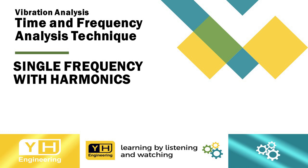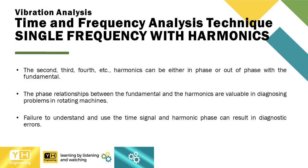Vibration analysis. Time and frequency analysis technique. Single frequency with harmonics. The second, third, fourth, etc. harmonics can be either in phase or out of phase with the fundamental. The phase relationships between the fundamental and the harmonics are valuable in diagnosing problems in rotating machines. Failure to understand and use the time signal and harmonic phase can result in diagnostic errors.